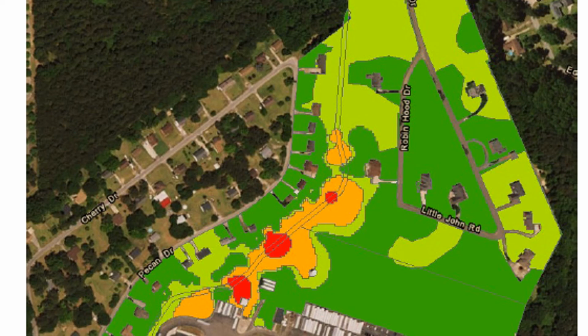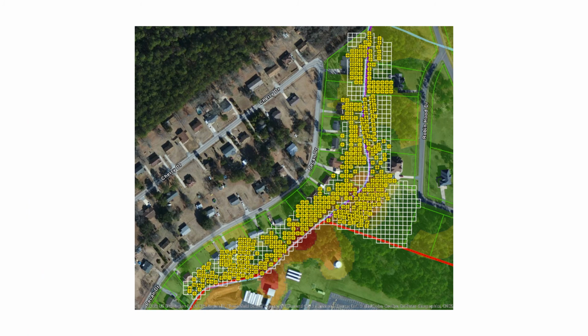An HRSC approach was used to collect high-density samples that could be generated in the field and used to refine the soil disposal disposition. Samples were collected at 20-foot by 20-foot grid at several depths to determine the nature and extent of contamination. Vertical samples were collected at 6-inch intervals.